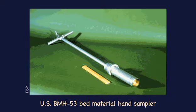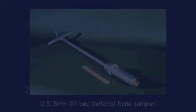The overall length of the sampler is 46 inches. The lower end contains a cylinder 2 inches in diameter and 8 inches long that is pressed into the stream bed to collect the sample. The suction created by the piston holds the sample in the cylinder. This sampler will not work for coarse sands and gravels. Its weight is 7.5 pounds.